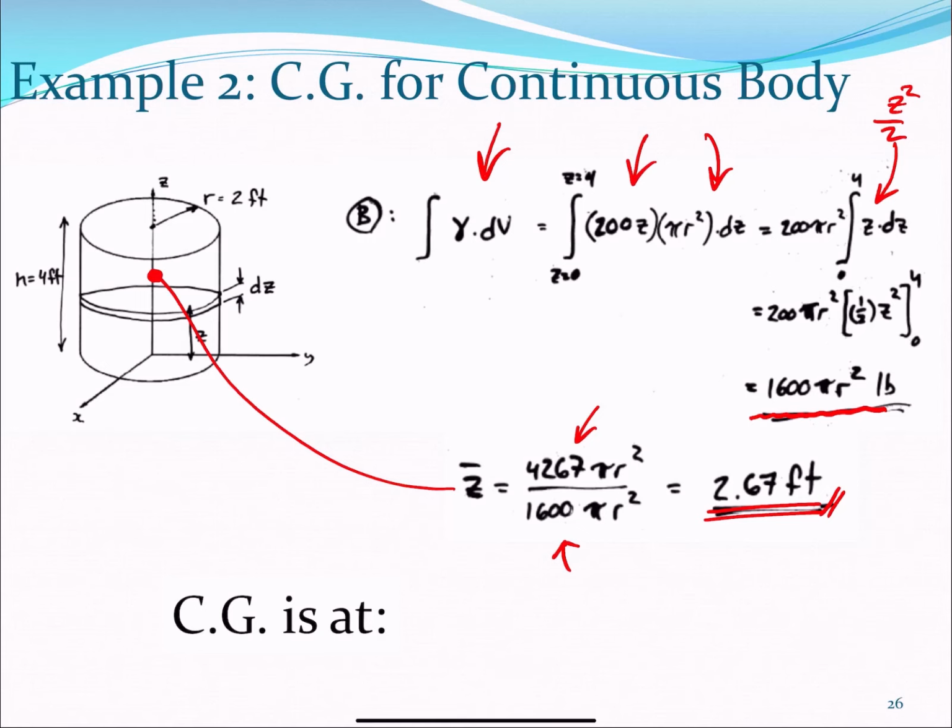So you have equations. Make sure you know how to set up your integrals with specific weight, with density. Sometimes a trial and error process will be needed until you get the same variable of integration in your integral. You have to have only one; you cannot integrate more than one variable, not at this point. There is multivariable calculus, but at this point you need to have only one variable. So make all the conversions, be creative, use the geometry of the shape, use whatever relationship between the variables you see, so as to efficiently set up your integrals.